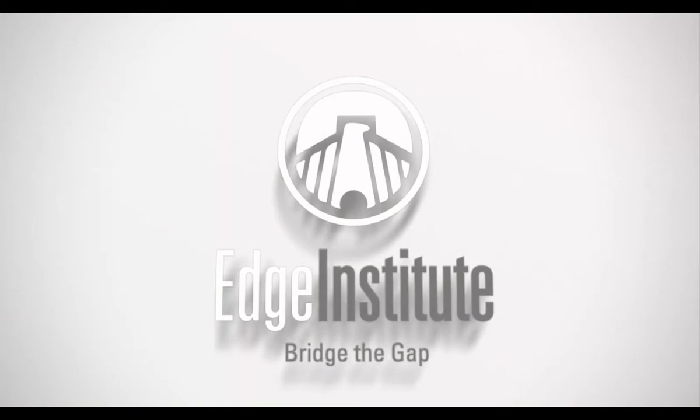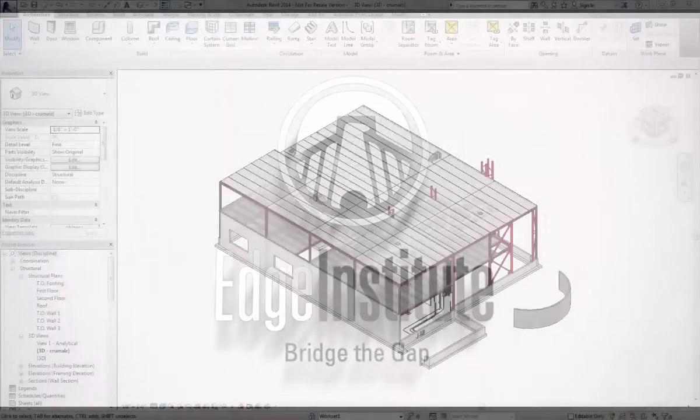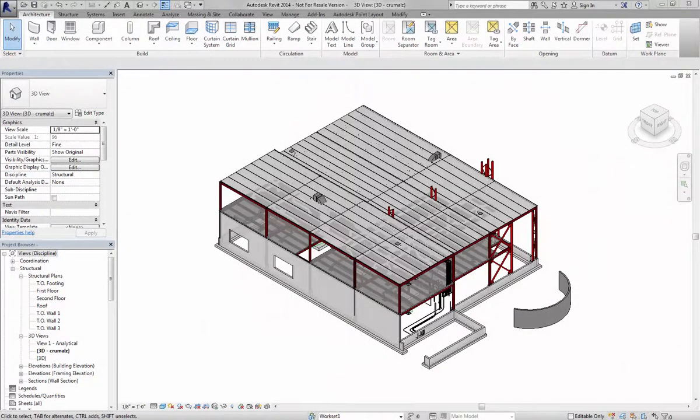Today we will be discussing Autodesk Field Layout. In this video, we will learn how the field layout workflow helps with the process of taking a 3D model and using it as a construction layout tool. Every trade contractor can utilize this tool to develop their layout plan by taking the points from the model to a total station to lay out those points in the field.